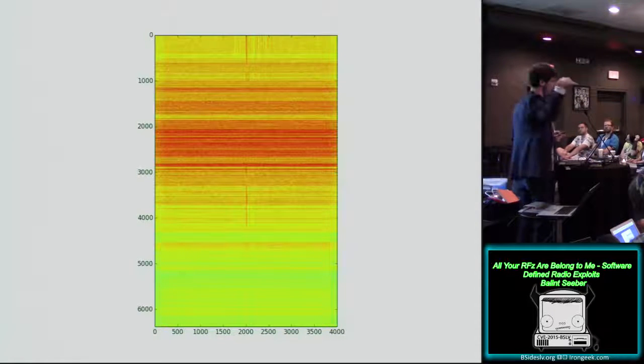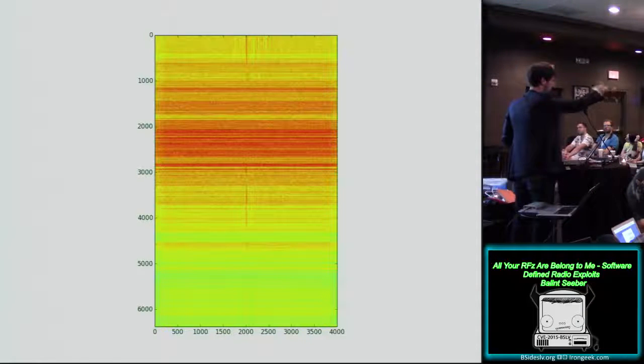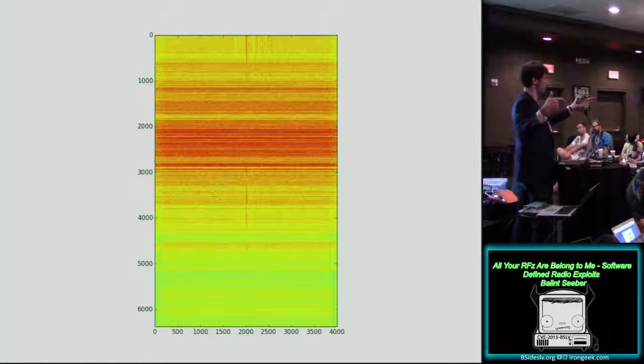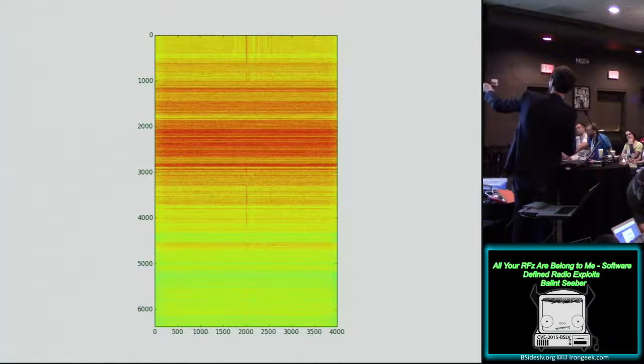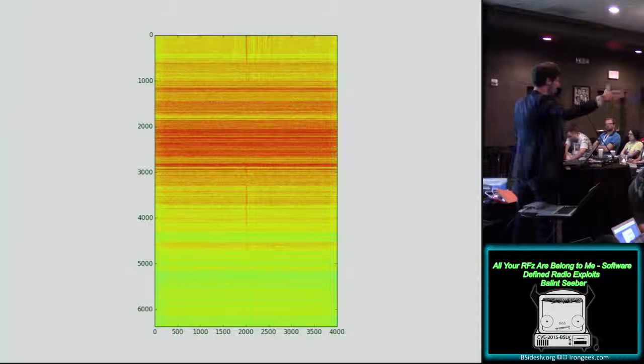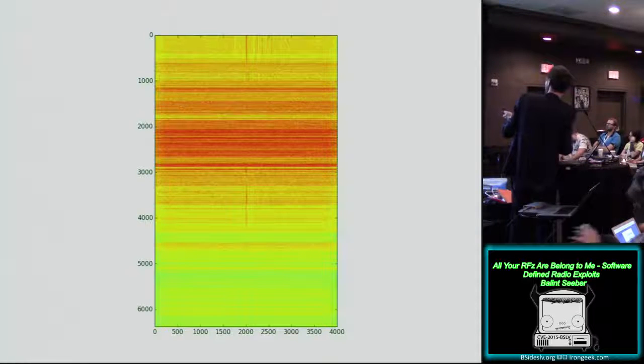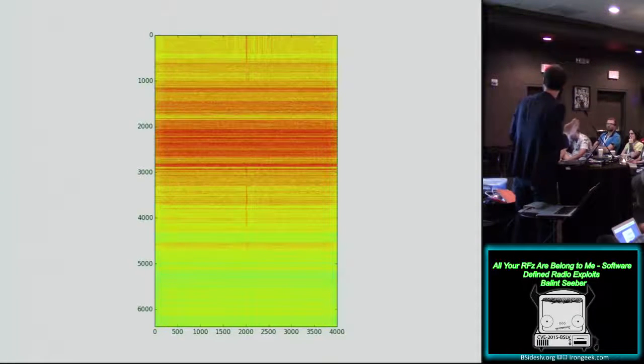And as I'm traveling down the highway, the distance from my car to the building to the transmitter is going to change, right? Because now I'm moving. So there might be an instance where I end up getting closer and closer to the building that's reflecting the signal. So my path is going to become shorter. And so I might see some extra lines popping up here that are actually diagonal now, because that multipath propagation distance is changing. It's a little bit difficult to see. I haven't really vetted these results too much, but I think if I zoomed in, there was some little diagonal line in there. So I think there was some effect there.